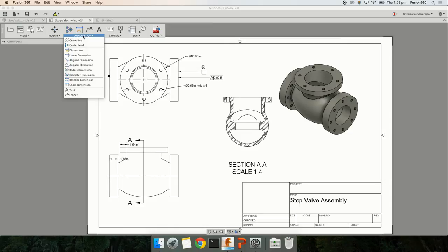Also, for the radial and diameter dimensions, there are defaults for the smart dimension tool too, so you'll have to flip it around. If it's a full circle, it's a diameter, or an arc if it's a radius. So I think giving access to the standard tools just makes it more convenient when you know exactly what you want in that scenario.